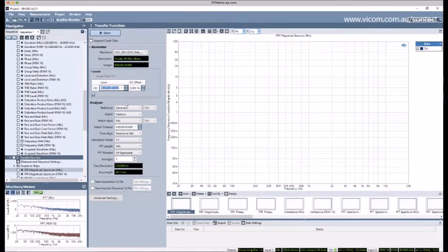So I'll just quickly say here that 114 dBSPL set in the signal generator will get me what I expect for this speech signal. I think we have a blog post on our website that talks about how to find the crest factor and set a generator level depending on the non-sinusoidal signal you're generating. But for this moment, we'll just set this at 114.